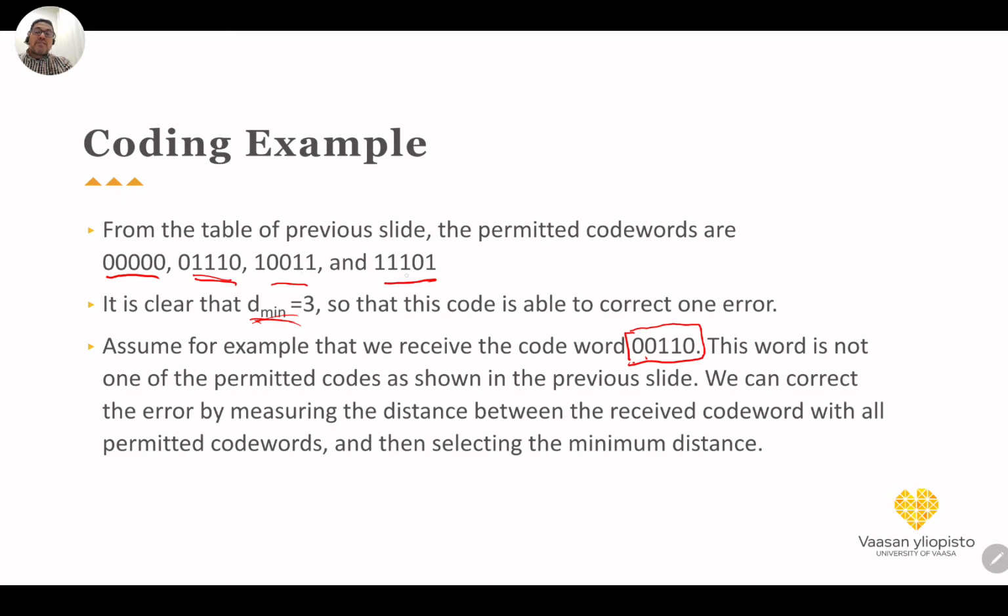And also the Hamming distance with the third one is, you can see, 1, 1, and 2, 3. So it will also be 3. So the Hamming distance is 1 only with this code, which means that the bit which was in error is the second bit. It was 0, 1 here, it was 0, 0. So the decoder will correct this error. All it does is only correcting this error.